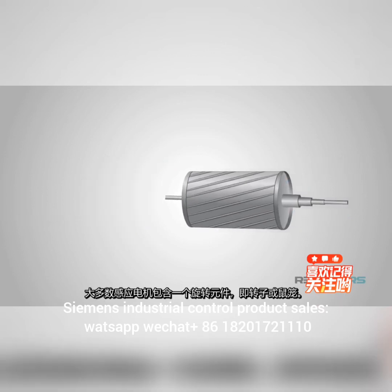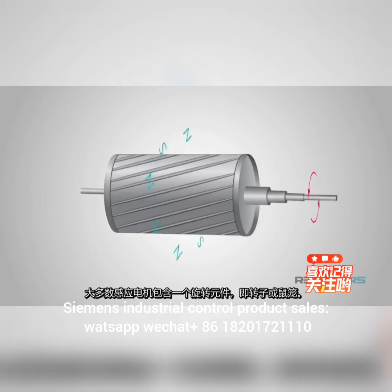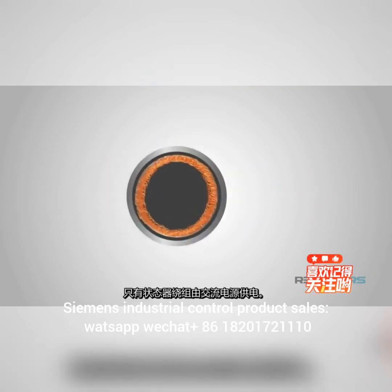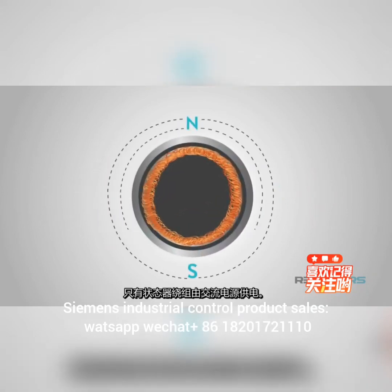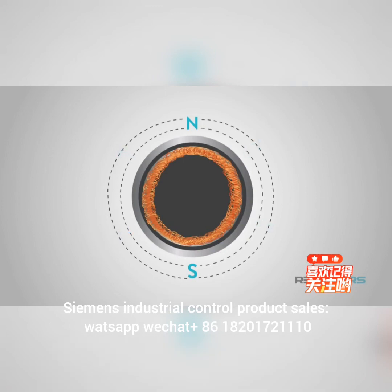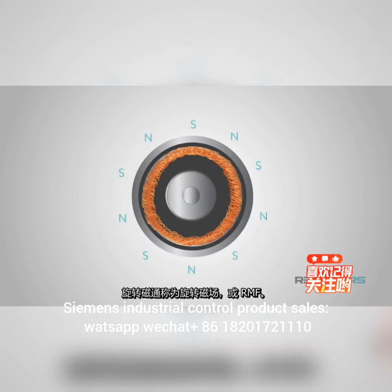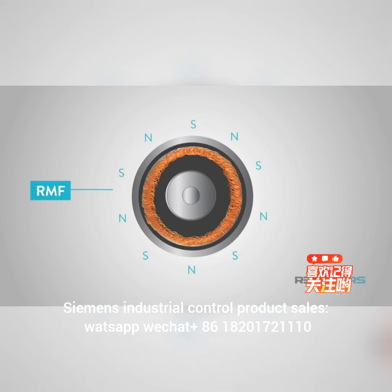Most induction motors contain a rotational element, the rotor or squirrel cage. Only the stator winding is fed with an AC supply. Alternating flux field is produced around the stator winding with the AC supply. This alternating flux field revolves with synchronous speed. The revolving flux is called a rotating magnetic field, or RMF.